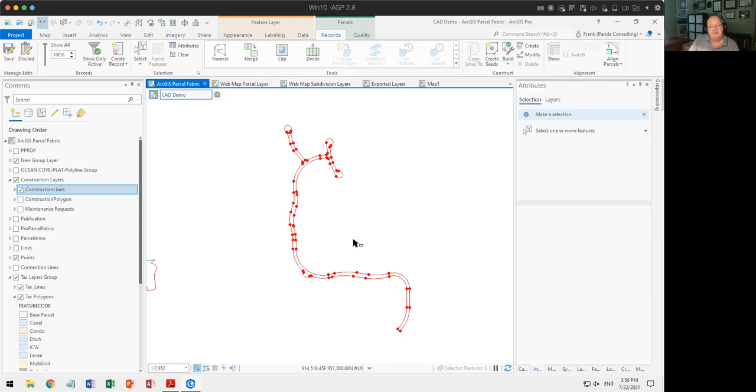There is some complexity in there, but most of us are just going to look at taking these lines and bringing them in, identifying which lines we have to bring in, recognizing we have to copy and paste them into a layer that we can work with them. You cannot go and edit the CAD lines. Once you get over that, it looks like you're working with any sort of simple feature class that you can go and manipulate and use. They act exactly the same, but you do have to know that it has to be copied and pasted in.